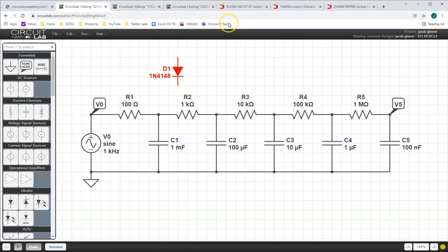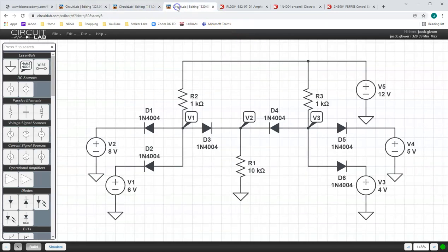When you have a diode in a circuit, kind of like this guy, I now have the same problem I had back in Circuits 1. I can set up n equations, n unknowns to solve. However, these equations are nonlinear. Solving nonlinear equations is a lot harder. So a diode is two types of silicon put together, P and N.